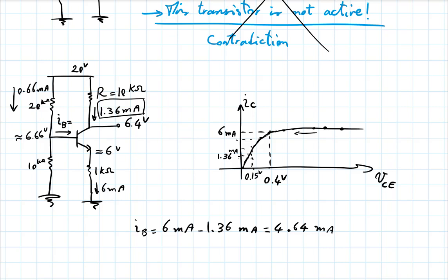That's the point where the collector current cannot keep up with the emitter current anymore, and the difference has to come from the base. That's when your base-collector diode is becoming forward biased, and it's starting to have a current. And that current is now sent through the base.